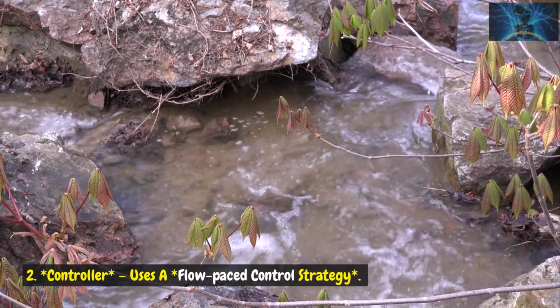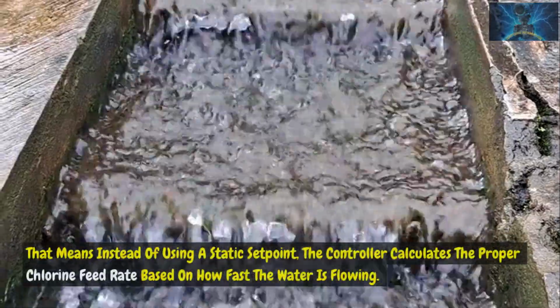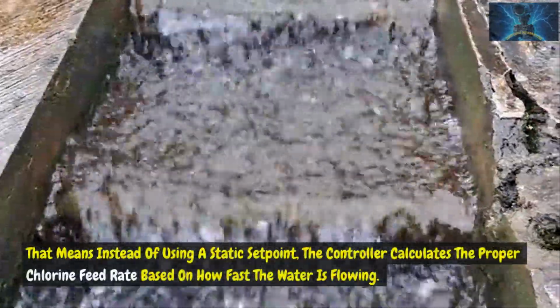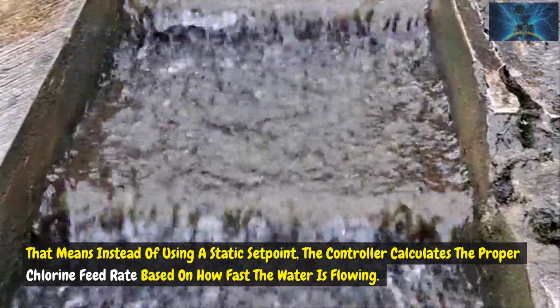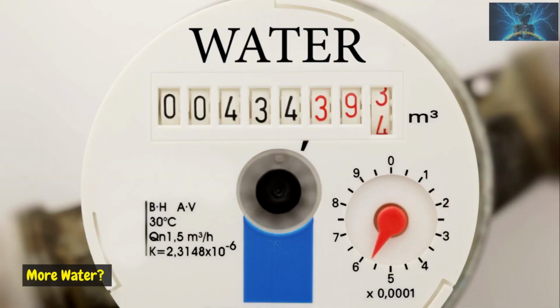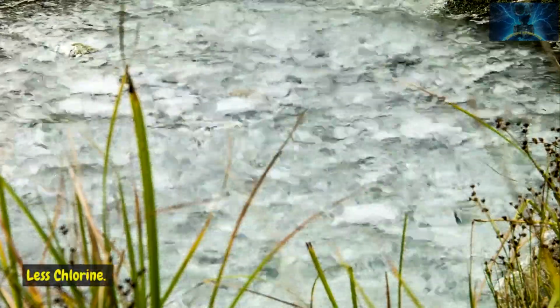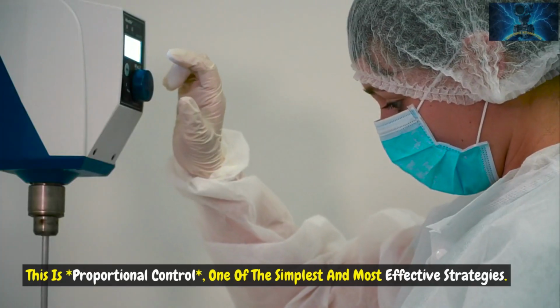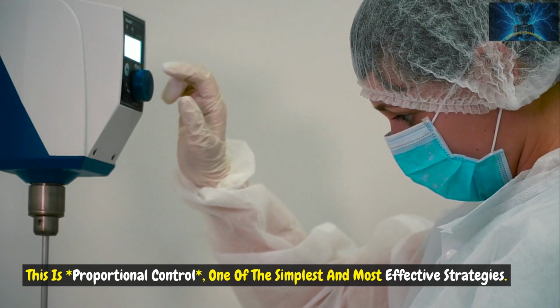A controller uses a flow-paced control strategy. That means instead of using a static set point, the controller calculates the proper chlorine feed rate based on how fast the water is flowing. More water? More chlorine. Less water? Less chlorine. This is proportional control, one of the simplest and most effective strategies.